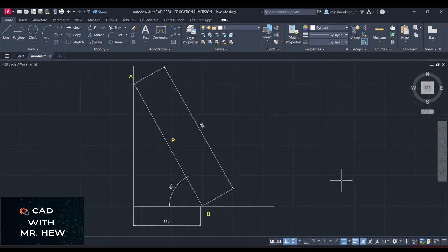All right, so there we have measured the length of the ladder, and it should be 230 millimeters when you set out the 110 from the wall and set out the 65 degrees. So what you're going to do, you're going to mark an arc from the intersection of the wall and the floor, going 230 millimeters away from the wall, because the ladder A would be at the end of the wall when it is horizontal to the ground, resting on the ground.